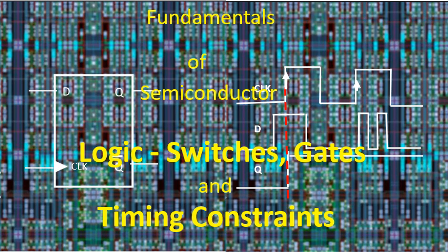MOSFET switches and logic gates are the fundamental digital electronic devices that create combinational and sequential circuits. N and P MOSFETs, operated in various configurations, create pass transistor switches, transmission gates, latches, and flip-flops. These basic building blocks realize digital functions like data storing, control, and computation operations.